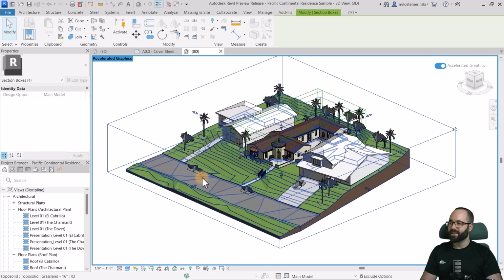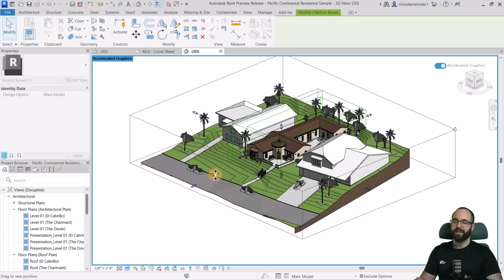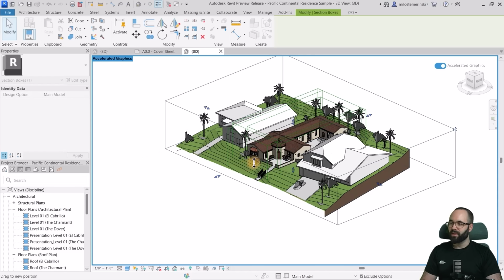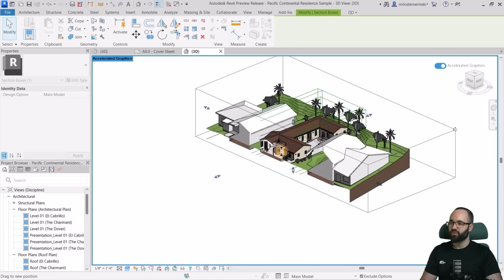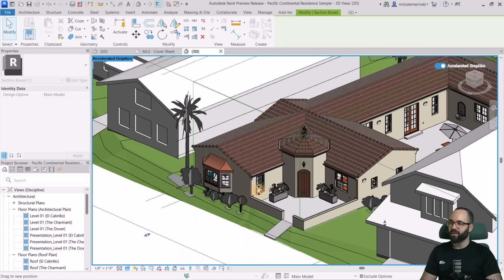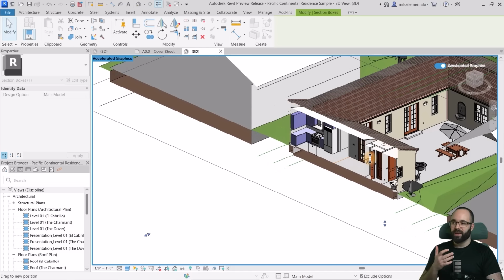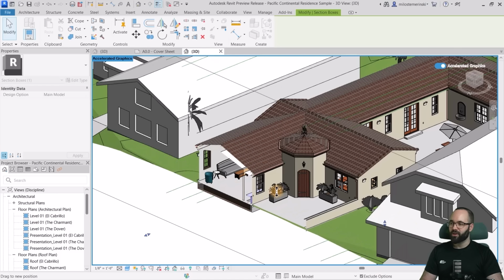box. So when you apply a section box, before, when you cut, it basically just showed you the end result; you had to release. Here, when we cut, as you can see, it goes straight through and shows you what's going on as you're cutting. So it's a lot easier to set up your section box like this when you can actually see what's going on when you're cutting.